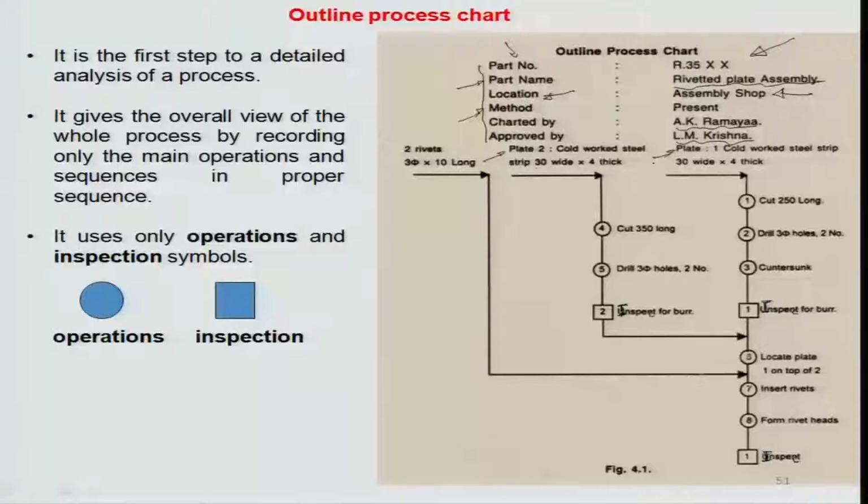So take both the sheets, lap one on top of the other, and then use a drilling mechanism to drill for insertion of a rivet, and then form the rivet head, so that you have a proper lock between these two sheets in terms of a rivet. So this is the whole operation, and for doing this we have three different things which are needed.